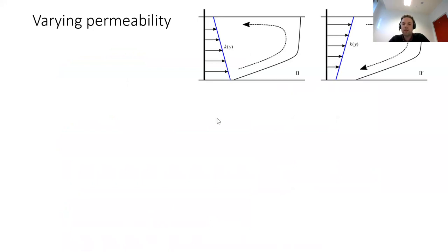Okay, so that kind of shock, where you have a fixed extent region and a growing region, occurs in two modes. You can have the case where your input fluid is of relatively low viscosity, as in the case here, but the permeability is low at the top. So for a low viscosity input, you would get in a uniform aquifer a growing viscous finger, but the low permeability at the top suppresses that, and you get a mixture of a growing region and a fixed region.